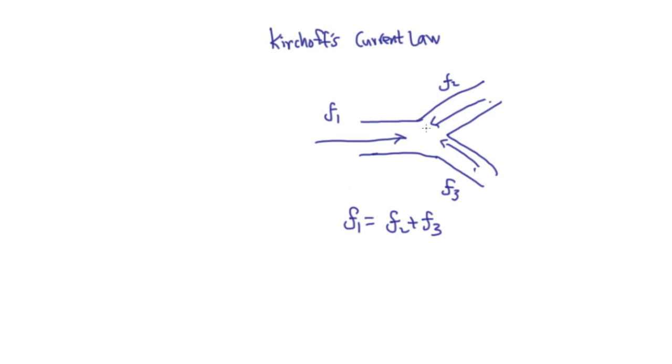So inherently, at this one node point, which is right here, this is a node. It's exactly the same thing as we discussed earlier with these wire connections: the exact same node, they have the same voltages. The idea is that at these nodes, the total sum of current that goes in is equal to 0, because everything that goes in must come out. That's the inherent idea of the Kirchhoff current law.